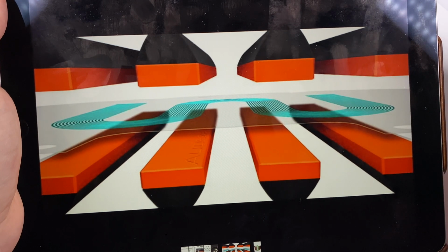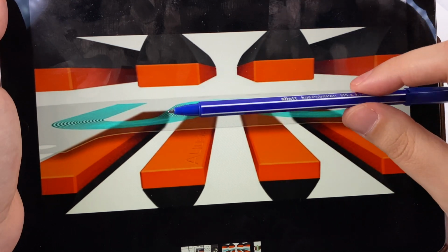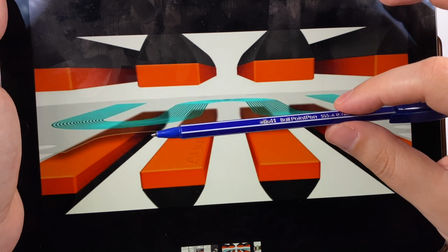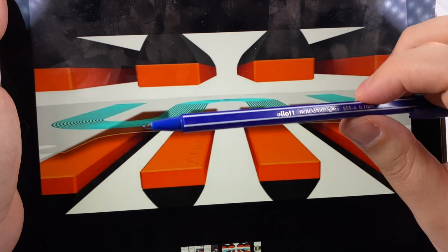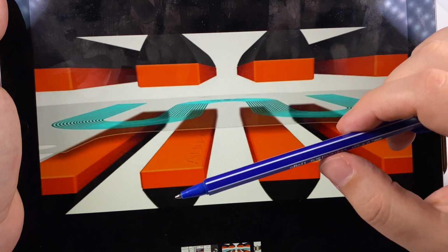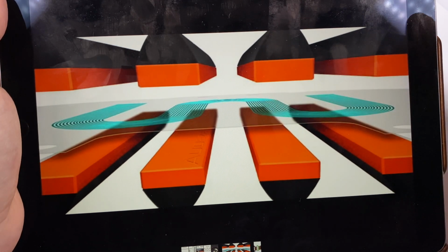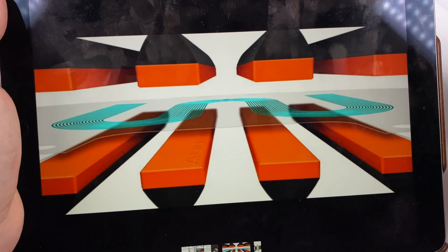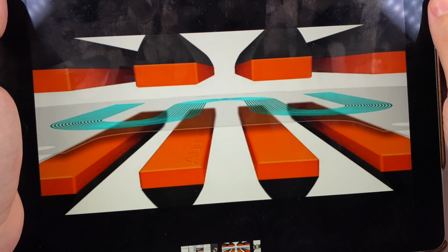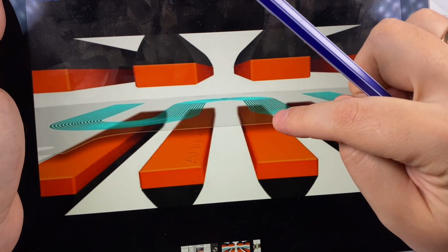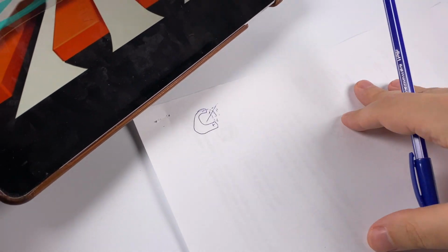The main minus of this schema is that it usually requires more power to drive it. Not as much as electrostatic schemas, but more than regular dynamic and balanced armature drivers. But that's what everyone knows here, like for planar magnetic headphones we need more driving power. So planar magnetic drivers can be isodynamic or orthodynamic. It's basically the same, just a different shape of these conductive wires on the surface of the membrane.